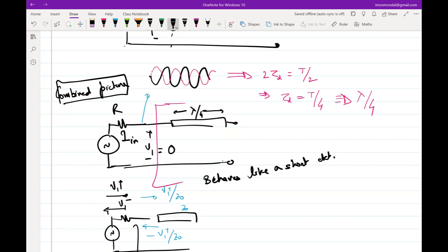And that's just an example, but I would argue it's the other way around, the problem is at the other end. We cannot use it at a lower frequency because lambda becomes very high. You cannot use this on a chip for a 1 gigahertz solution. Then lambda becomes a few centimeters and your chip sizes are maybe 2 millimeters square. So that's why in most RF applications you see tuners that are pretty big. If you are dealing with circuits of a few gigahertz, sub 10 gigahertz, naturally they have to be big in size. So very often tuners are off chip so that you can do the impedance transformation the way you want. So the problem is at the other end.